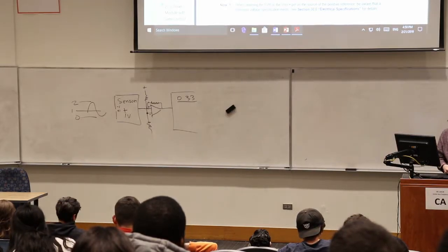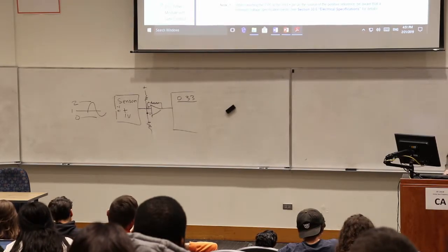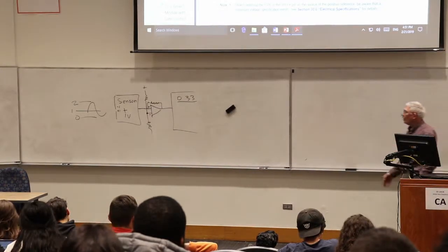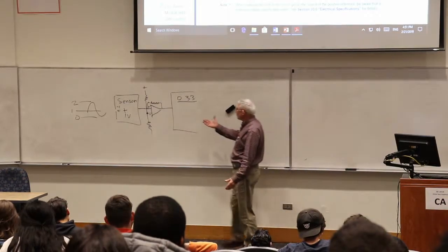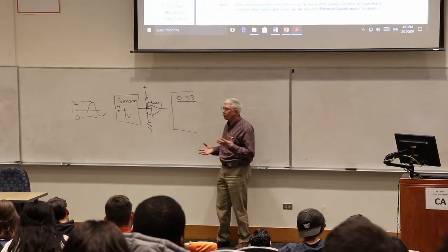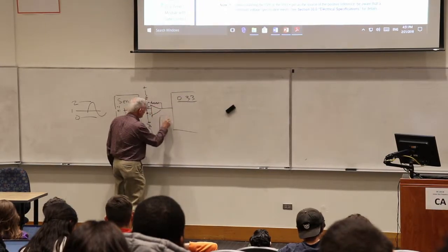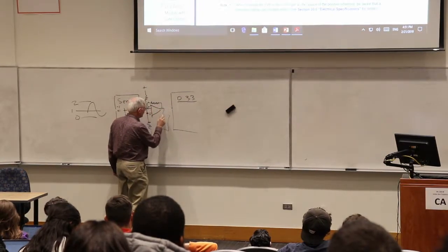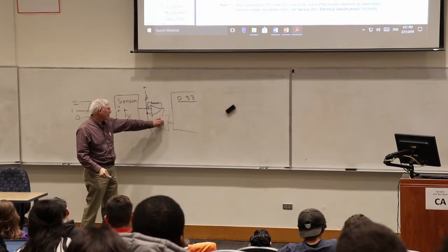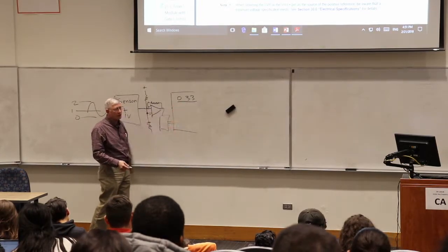And remember also that your op amp has slew rate limitations. So if you have a very high-speed signal, you need to make sure your op amp matches your signal. And if you need a big bandwidth, you need to make sure your microprocessor can handle the bandwidth you need. Most microprocessors are somewhat limited, and so sometimes we'll have a standalone A to D module that will actually feed this in, and then we'll feed that in to the microprocessor on a digital line. So this will actually do the conversion here, and then send in a digital signal instead of using an internal A to D converter in the module.